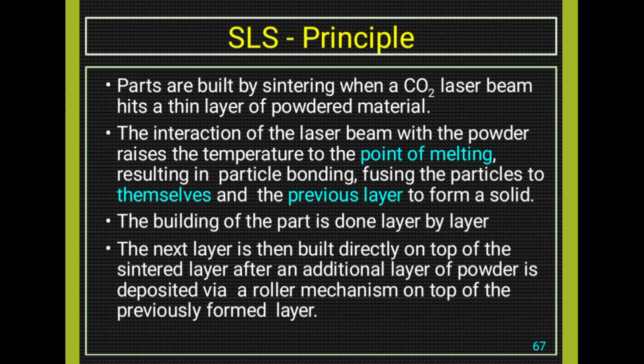First, we shall see about the principle of SLS. In this process, the parts are built by sintering when a CO2 laser beam hits a thin layer of powdered material. The interaction of the laser beam with the powder raises the temperature to the point of melting, resulting in particle bonding, fusing the particles to themselves on the previous layer to form a solid.